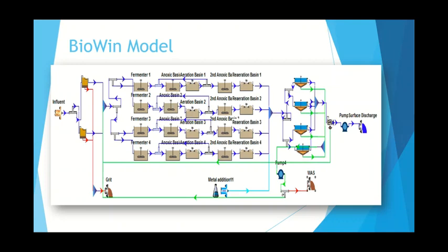The top portion of the clarifiers goes through a dewatering unit before being pumped as the effluent out into the surface water and/or groundwater. The bottoms of the clarifiers allow the sludge to settle and is pumped to be recycled or wasted as defined by the split ratio. The red arrows represent waste and the green arrows represent recycled streams.